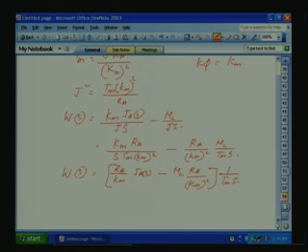So the whole purpose was to introduce the electromechanical time constant. The J factor is also inside this Tm. Now, let us rewrite our block diagram and modify, find out our transfer function.